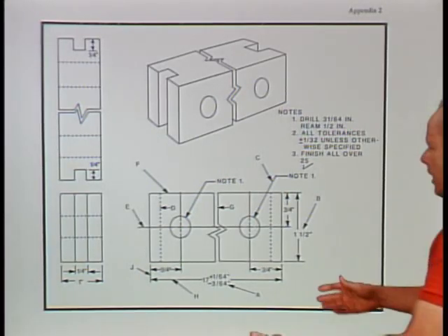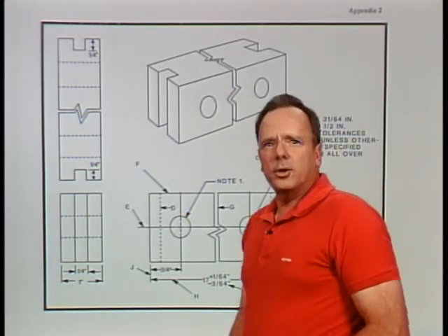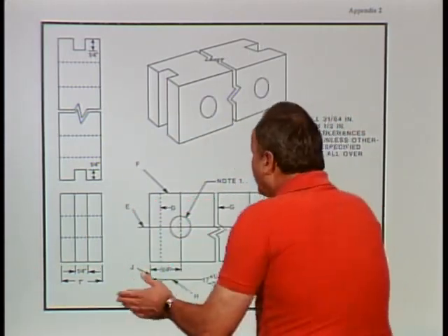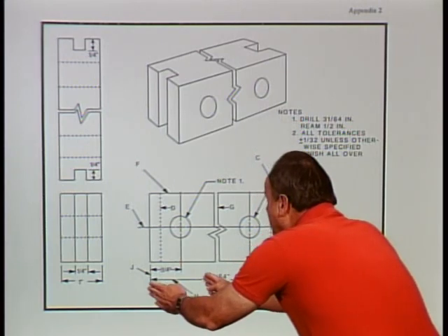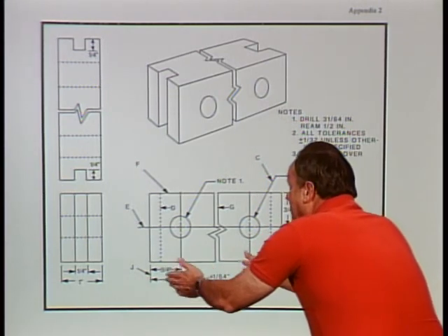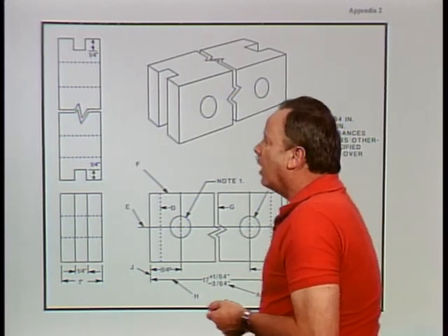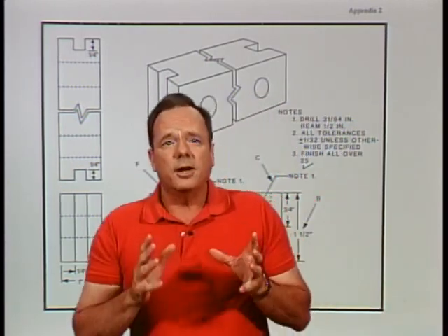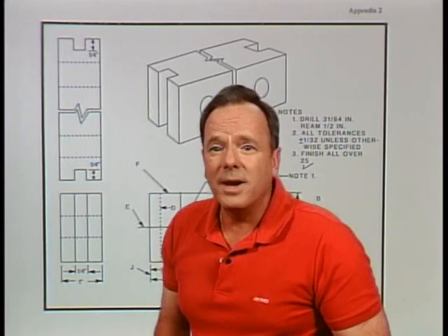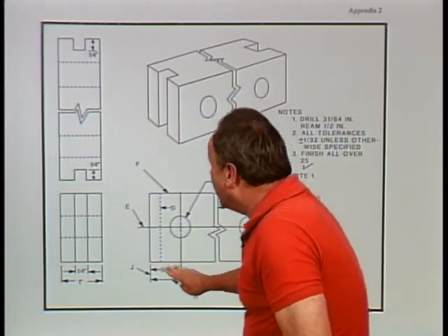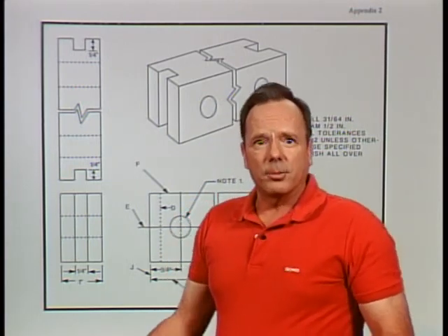And once again, in this case, number 3 is the section line symbol for cast iron. Now let's assume you're looking at a chart like the one on figure 36 and you'd like to know some measurement off that chart for some item here. Well, the way to do it is to read the dimension off the chart, and if you need to figure out some distance, calculate it, but don't use a scale and measure or scale off the aircraft print, because the paper shrinks or stretches when it's made, and if you just try and scale off of it, it will not be accurate. So measure or calculate dimensions, don't try and scale them off the drawing.